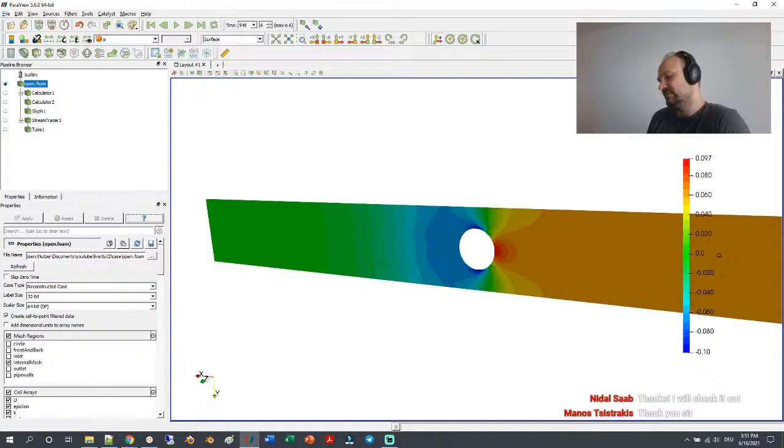I'm not a Salome expert, so I think some of the viewers have more experience in Salome. In Blender, what I do, I mesh it manually, export it as an OBJ, and I extrude it for 2D cases. Sometimes it even works for 3D if you can extrude it. So it really depends on the problem.